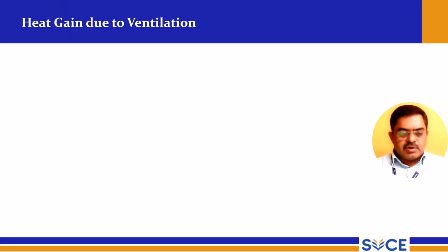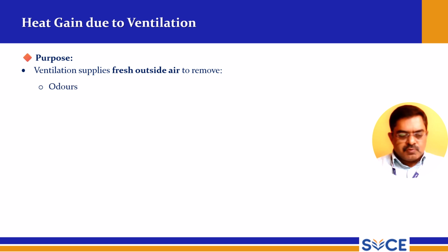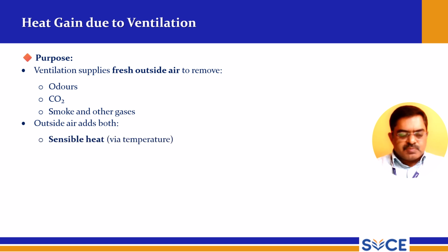So, heat gain due to ventilation. The purpose of ventilation is to supply fresh outside air to remove odors, carbon dioxide, smoke and other gases. Outside air adds both sensible heat as well as latent heat, via temperature and via humidity.